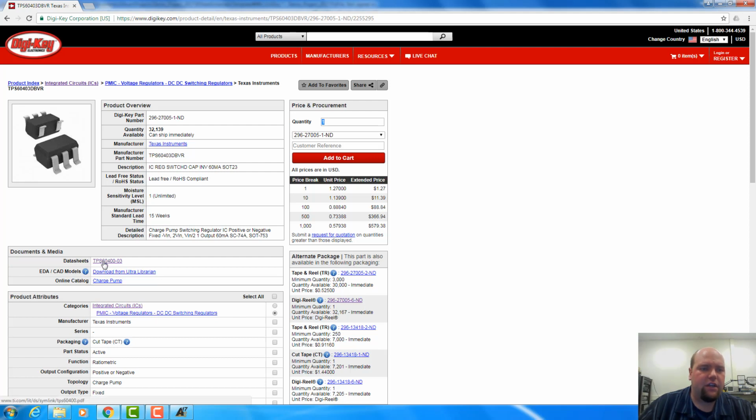So let's look. This is the part that I pre-shopped around for a switching regulator to do this. This is on DigiKey. One thing to note about this part is it's only capable of outputting 60 milliamps. So this is something we have to keep in mind. Maybe it's something we should label on the board to say, hey, the output is whatever input current you had on the positive rail, but on the negative rail we're limited to 60 milliamps. 60 milliamps should be more than enough for most op-amp applications, but there are certain times where you might be using more current than that on the negative rail, in which case we'd have to use a different design.